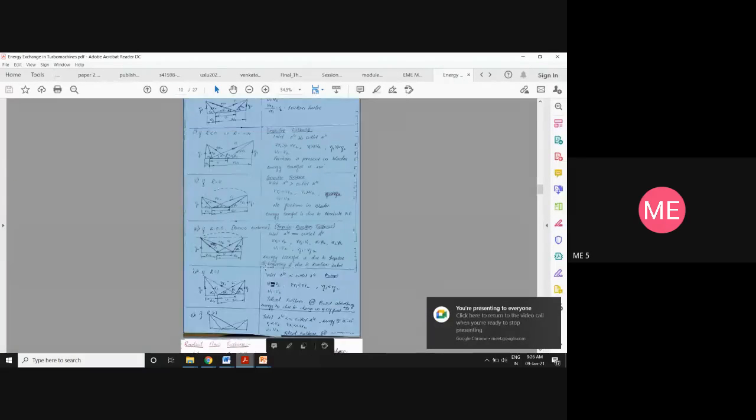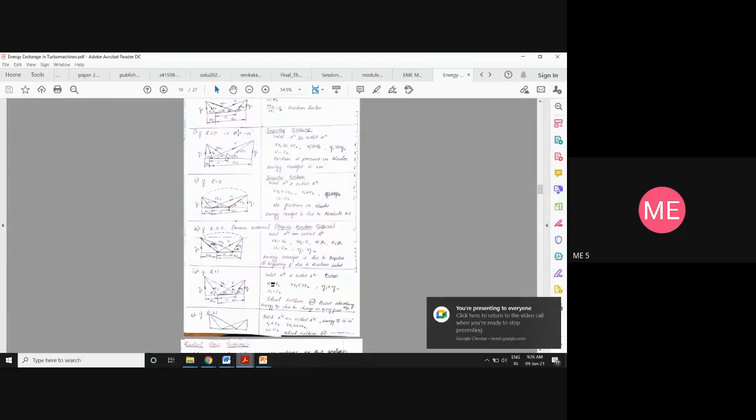See, why I'm concentrating on this more is because you can score good marks in this. Just by learning this drawing, this sheet, you can get 6 to 7 marks if they ask. They will ask for 6 to 7 marks: draw the different velocity triangles for different values of R. Or any 3 they will ask: R negative, R positive, and R equal to 0. Draw the velocity triangle. If it is negative, make the inlet very, very bigger. If it is equal to 0, then the inlet should be a little bit bigger than the outlet. And if it is positive, you try to make the outlet bigger compared to the inlet. That's all. Positive corresponds to pump, negative corresponds to turbine.